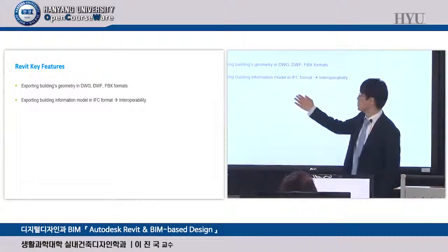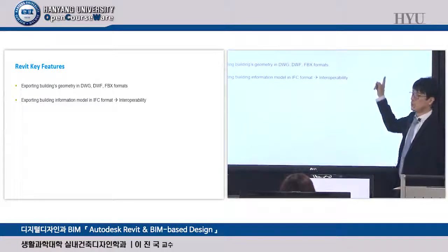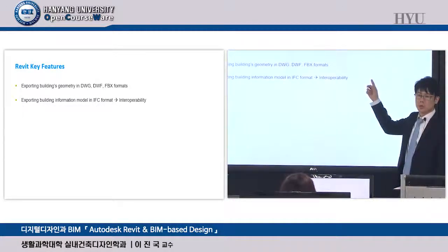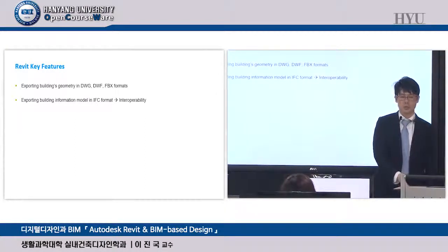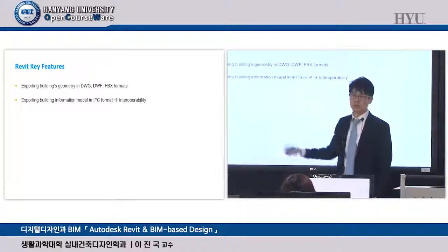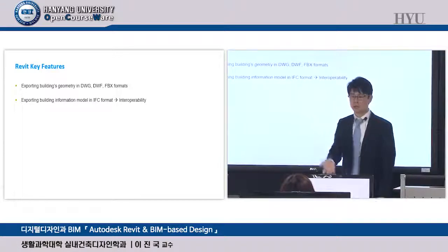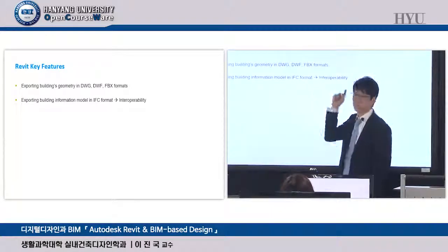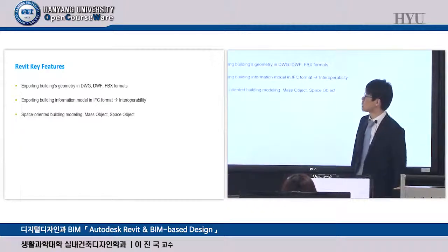So your BIM model can be exported through IFC and imported into another BIM tool. What happened? He knows your door object, wall object, curtain wall system object, not just geometry, okay? So this is another important thing, but at the undergraduate level, we're not going to deal with the IFC format. Instead, I'm going to show you some example cases.